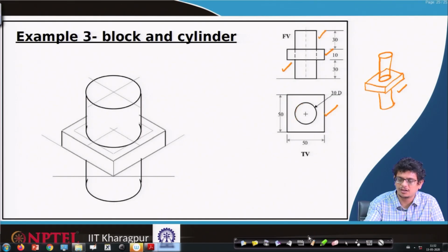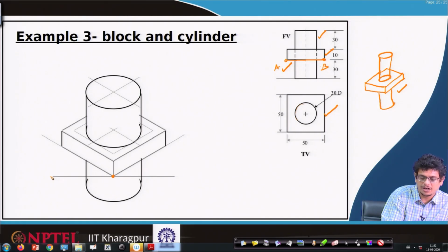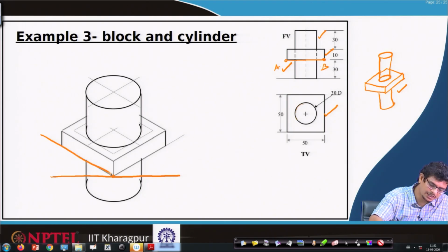So, we would like to begin this from the front view. If I would like to begin, then there is a length of AB units. So, begin with a horizontal line somewhere, draw a 30 degrees line, another 30 degrees line.